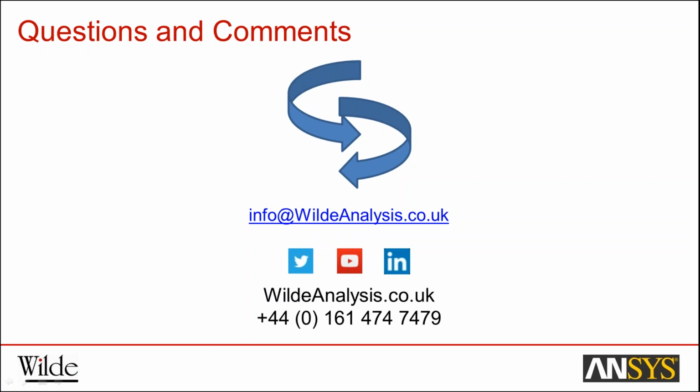Okay. With Design Explorer, we have a client here who would like to deal with things such as plate thicknesses, which I guess is not a continuous value, it only comes in discrete thicknesses. Is that something that can be done with Design Explorer? Yeah, that's definitely something we can do in Design Explorer. We have a tool called manufacturable values. So like the example that Brian mentioned, plate thickness, hole size for example.